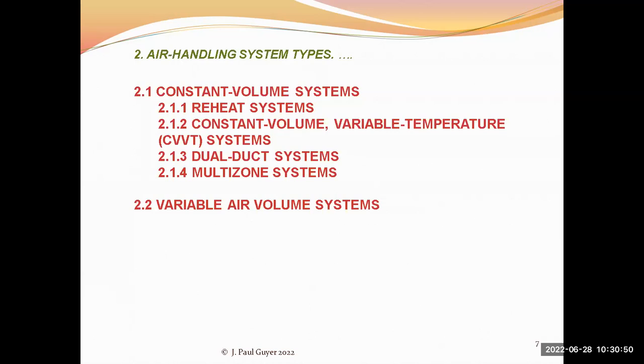But again, this is an energy inefficient system, because you have to use energy to heat the air in the hot air duct, and you need to use energy to cool the air in the cool air duct. And then you mix these together just before they discharge into the zones.